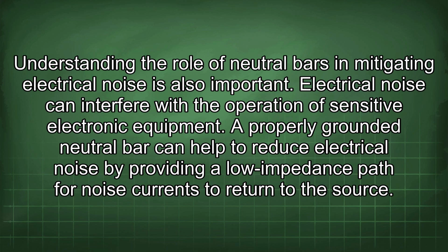Understanding the role of neutral bars in mitigating electrical noise is also important. Electrical noise can interfere with the operation of sensitive electronic equipment. A properly grounded neutral bar can help to reduce electrical noise by providing a lower impedance path for noise currents to return to the source.